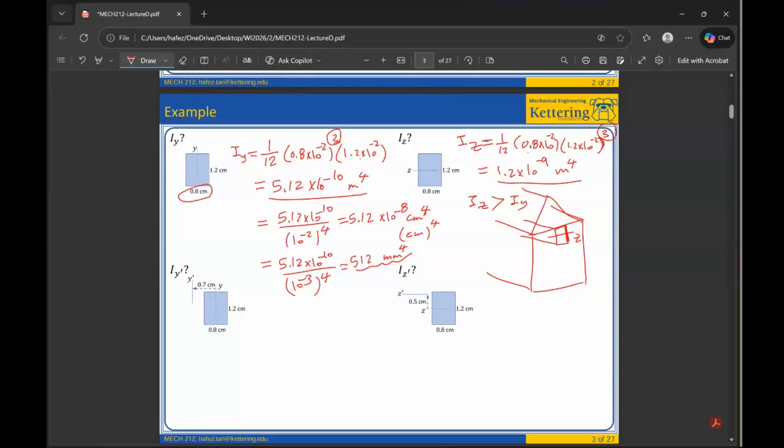So be mindful of that. Even though bridges are mostly flat when we walk on them, the thickness is less, but the beams that go into the cross section are actually oriented this way. All right, so that's the reasoning behind it. It gives maximum resistance to bending.